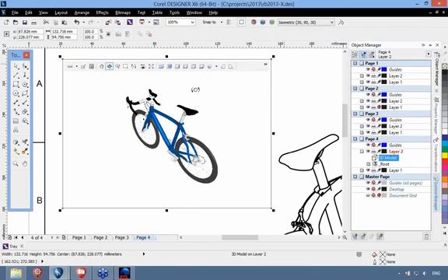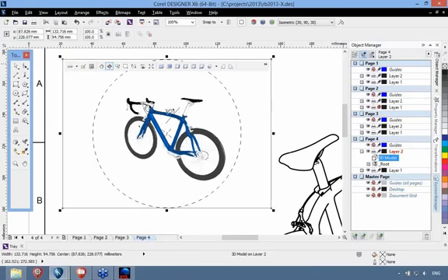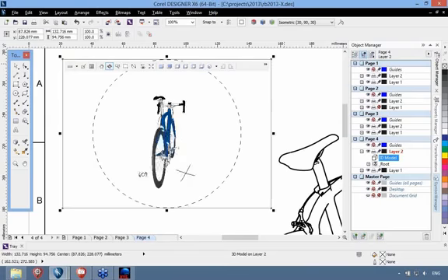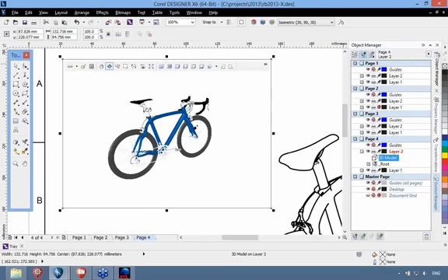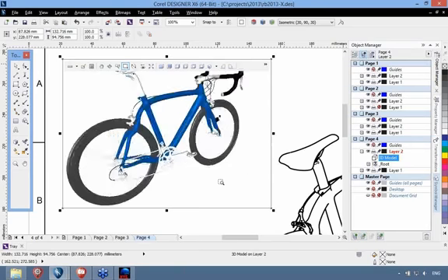With a double click, I'm in that 3D model now, and same as I did in my 3D visualization application XVL Studio before, I can now rotate, zoom in, do things like that to specify the view. I have a perspective view here that's appropriate as an overview that I want to include with my technical illustration.